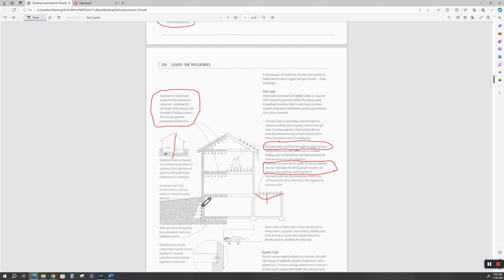The retaining walls. This represents the load. The deeper you go, the more soil that's down here, the more pressure you've got on the basement wall, or this is really a retaining wall, even though it's a basement wall. This wall carries all the load from up here down to the footing and the foundation. This shows a little gap underneath here.